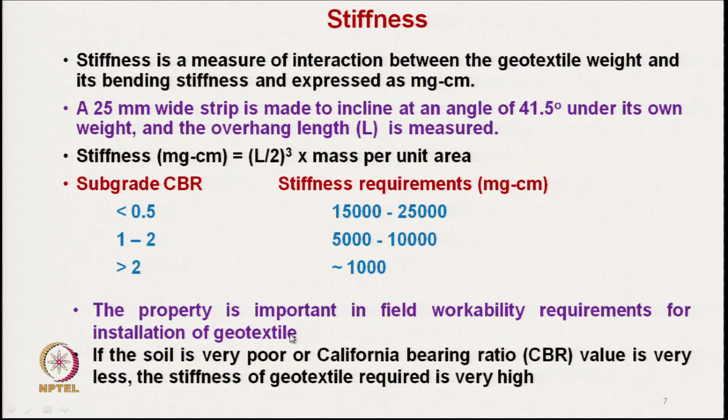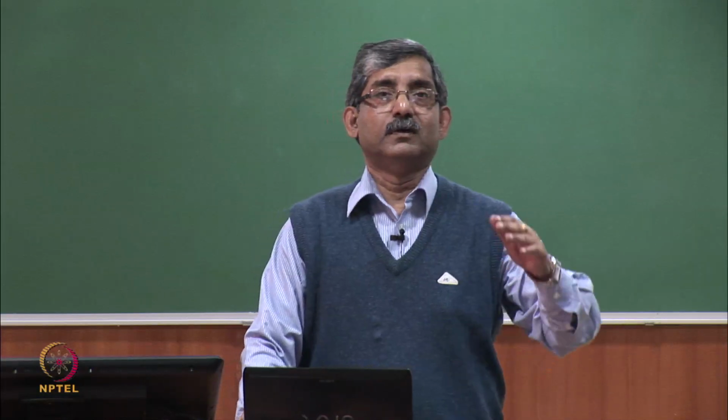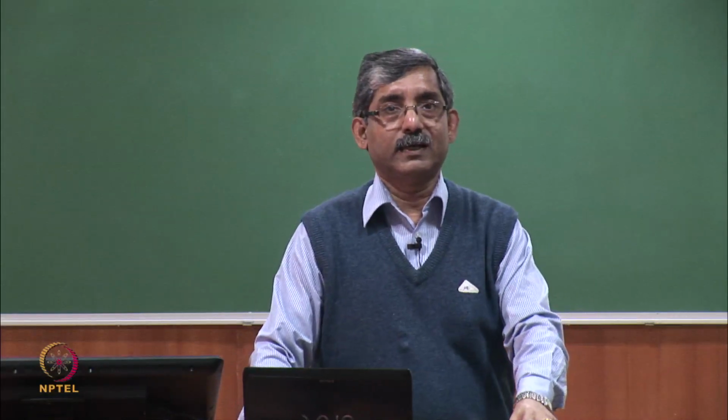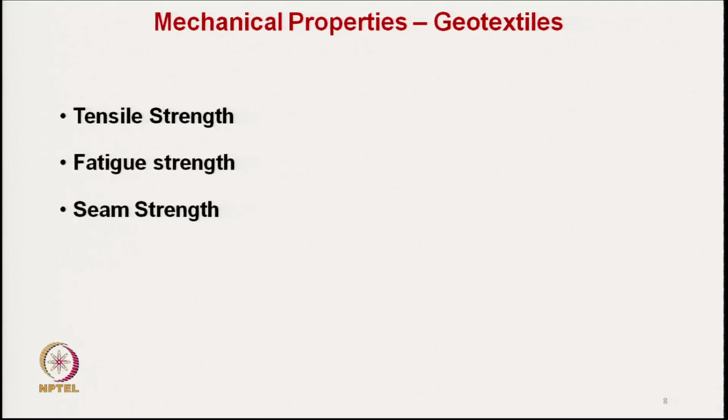The property is important for field workability requirement, as I have already discussed for installation of geotextiles. If the soil is very poor or the California bearing ratio CBR is very low, in that case we need stiffer geotextiles.